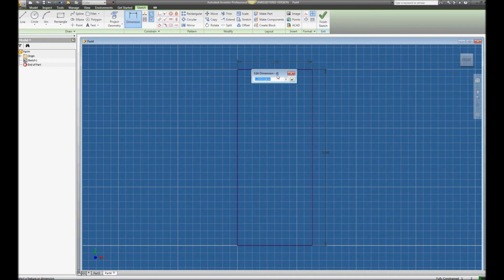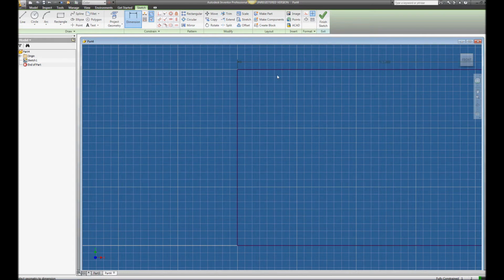And that's what our geometric relationship is. It's telling us that it's a ratio of 5 to 3 of the overall plate width to the overall plate depth. So, our equation is going to look something like this: D0 times, parenthesis, 5 divided by 3, end parenthesis, and there we go.